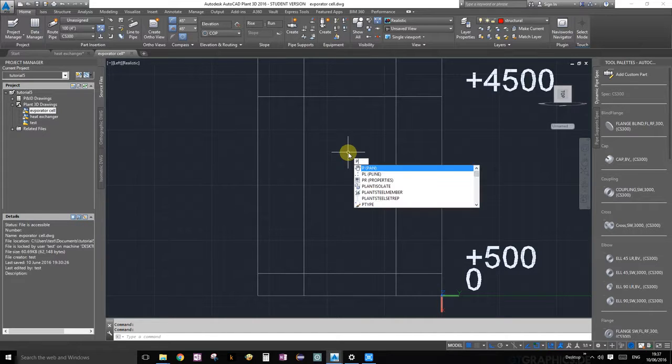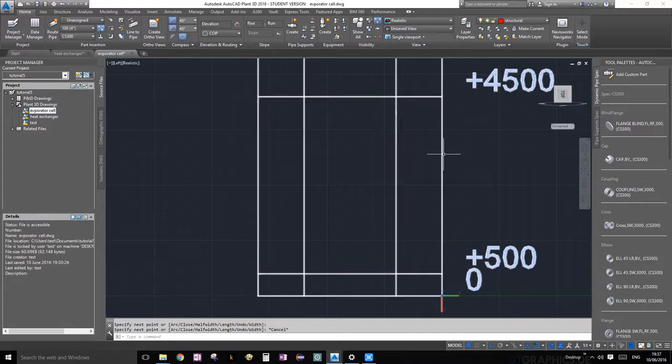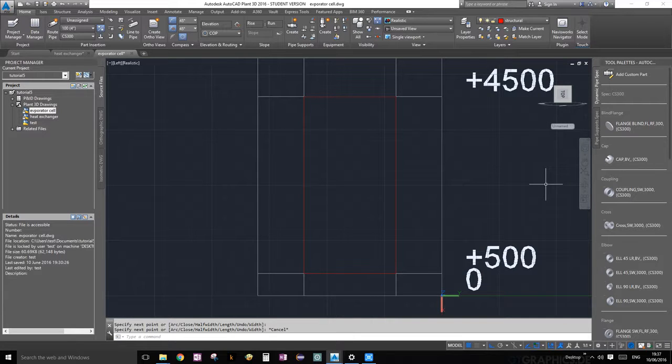Just start typing p-line, and as you can see, that's my second option. Press enter. It's going to ask you to specify your first point. So I'm going to just do so. Just follow along with me. There, and close it off there. Perfect. Now we have our first box ready.